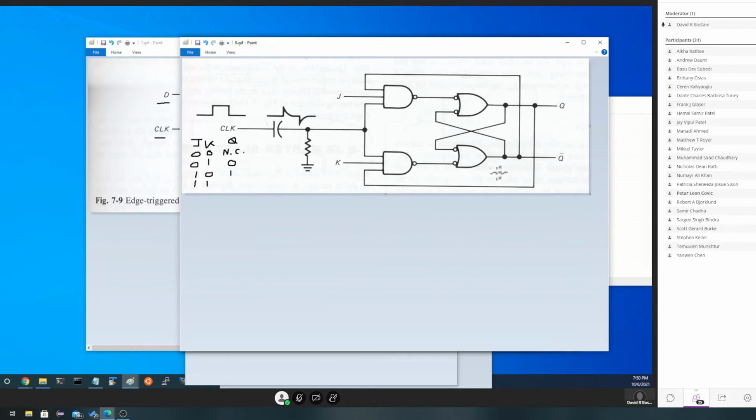And what they did there is they cross-coupled back. Notice the output of this winds up going over here. And the output of this winds up going over here, which means we get a new state. It was 0, 0. We now have a state called toggle.